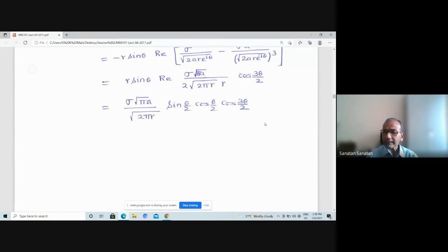And we have then adopted it in the case of crack problems. Crack problems like the center crack problem in a plate, where the problem has symmetry, and in that case it is possible that the solution can be obtained in terms of a single analytic function, which is known as the Westergaard function. And this Westergaard function was given in a simple form by Westergaard, and we adopted that Westergaard stress function, and then we got the expression for stresses, and then we have to now ask the question: how do we get the displacements?